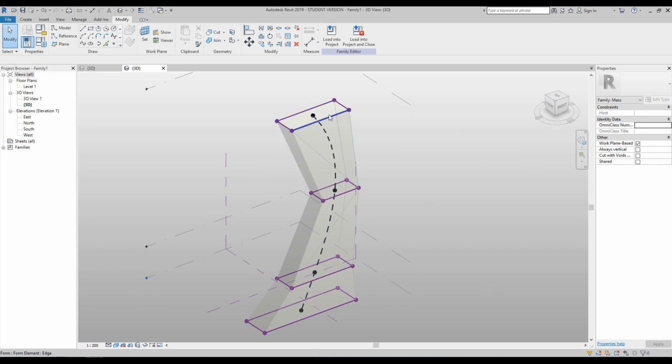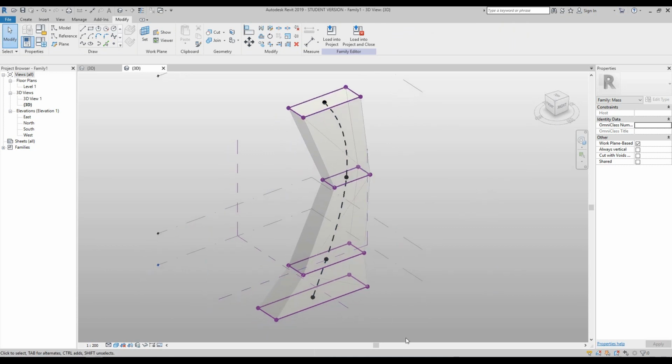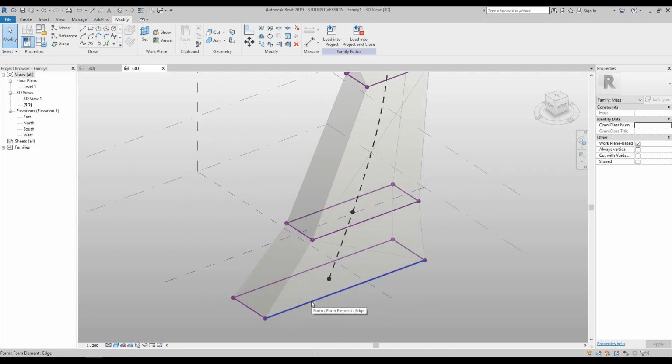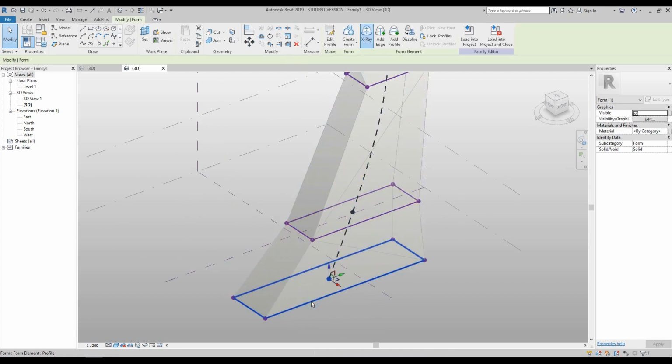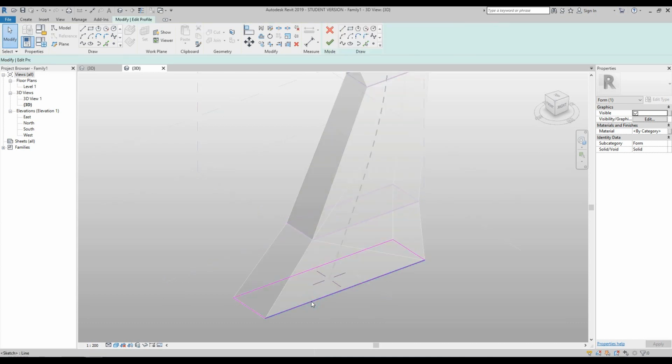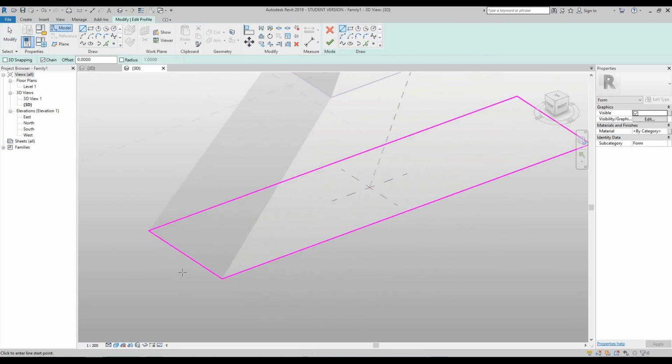Now don't forget, we can actually edit the whole sketch mode of our profiles. So to highlight that in further detail, let's highlight all 4 lines profile of the ground floor. Double click so they enter into a pink mode. The user interface will turn green. And let's add 2 more lines. So let's draw a line here and then an angle line to about here.